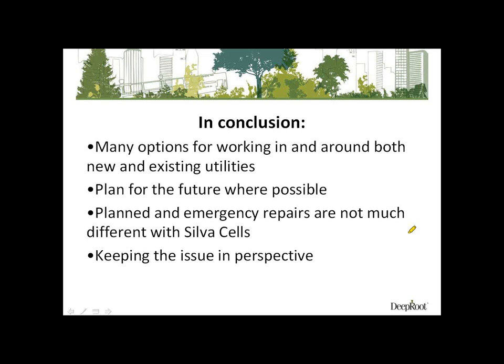Because of their openness, you're able to put pipe through very easily and connect up storm structures from one to another, or to put drainage in there if you're going to have something from the surface, like a pervious pavement. It's easy to put your drainage through.